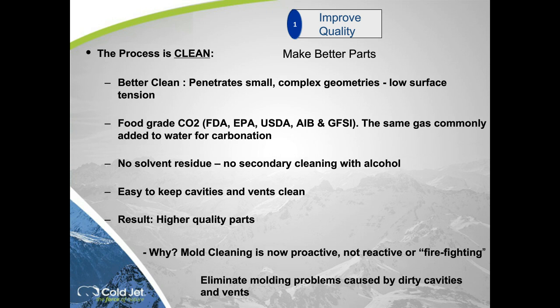Oftentimes, mold cleaning is delayed. It's postponed because it's just not a fun thing to do. It's a tedious thing to do, and it's time consuming. So people wait sometimes until there's a problem, and now we're firefighting. Because cleaning with dry ice makes it so easy, it allows guys to schedule it ahead of time before the problems start, to be proactive, and you can eliminate a lot of molding problems that come our way in molding and manufacturing medical devices because of dirty cavities and vents.